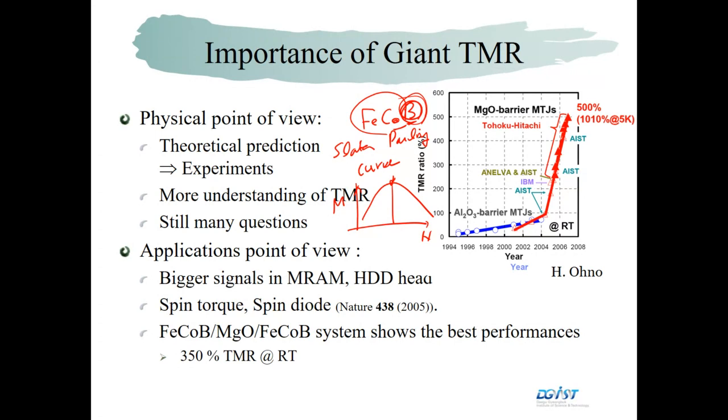When we grow polycrystalline material, there are grain boundaries, and these grain boundaries act as pinning sites during the magnetization switching. So with grain boundaries, the switching behavior is worse. With boron, at first we can make the amorphous phase, but after we anneal it, the boron is diffused out, and then the grain boundary effect is minimized. So the role of boron is something like that.